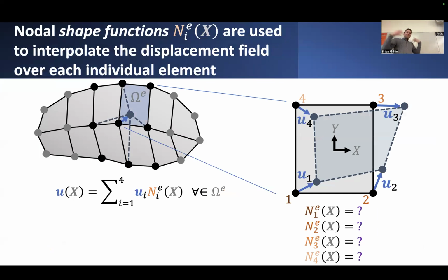Now, basis functions are really the things that have to vary over the entire domain. But there's this other related concept, shape functions, which are really nothing more than the basis functions for a particular node, but defined over a specific element. So when I talk of shape functions, I'm really speaking of nodal basis functions, but restricting attention to some specific element.